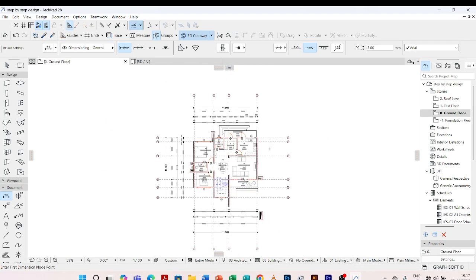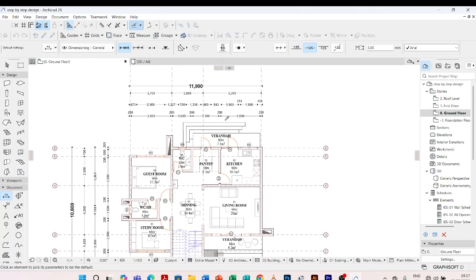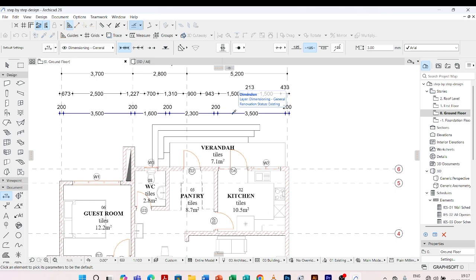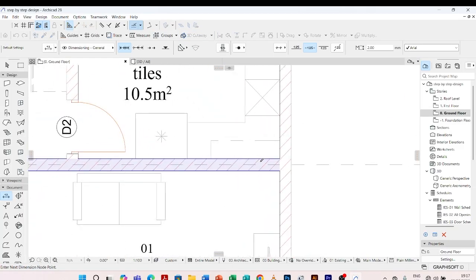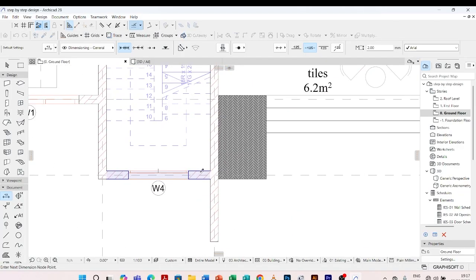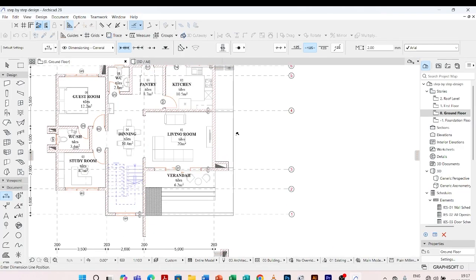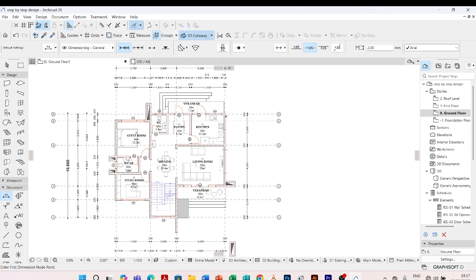We are going to do the same on this side. I come to the pickup parameter tool, I click on it, I come pick parameters of this dimension line, click on it, I come dimension of my walls. Come click in this space. The next dimension line is for our openings, but since we don't have any opening in this elevation, we shall go with that line.